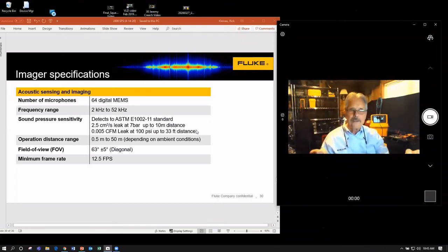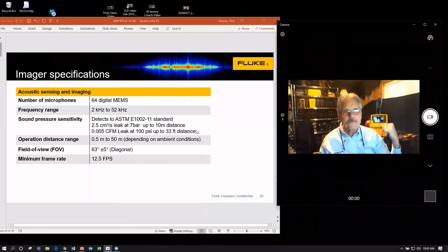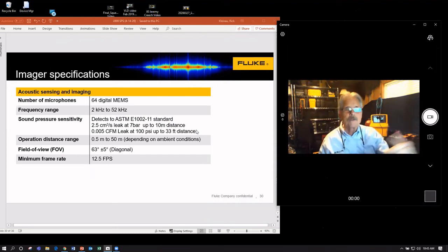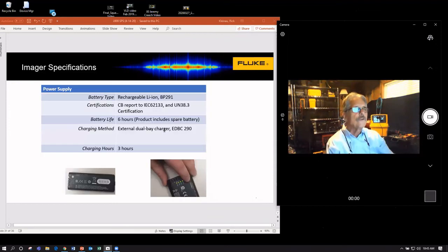You're sitting at a stoplight and you hear somebody's bass booming in a car 40 feet behind you, boom, ba boom, the high frequency sound is gone. It's just the low frequency stuff that's made it to you. So sometimes finding a leak at a distance, you'll drop that frequency band. And as you get closer to it, you can get better resolution.